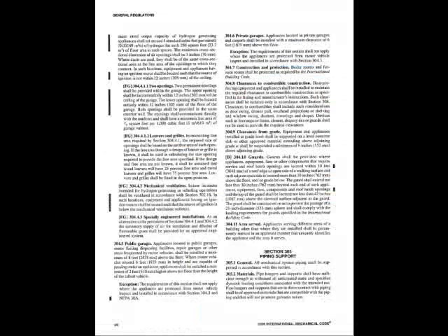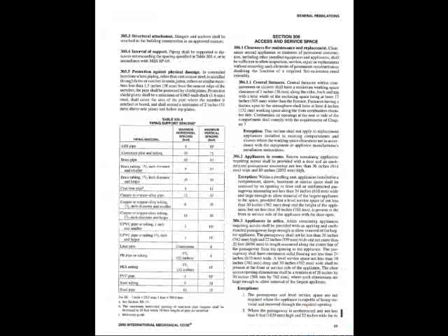Section 305 talks about piping support. All mechanical piping shall be supported in accordance with this section. You can't just hang piping however you want. It talks about the proper materials. It talks about the piping hangers that are in contact with piping. We cannot have galvanic actions.